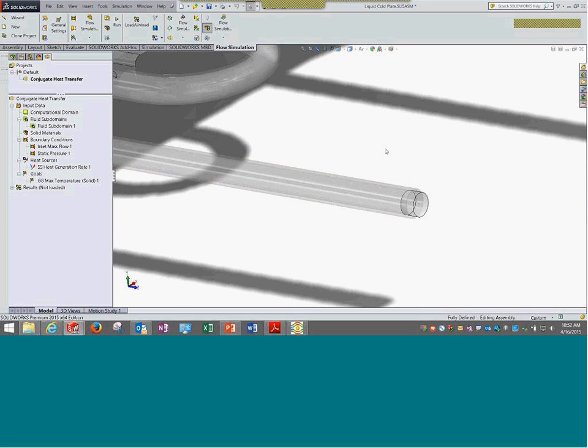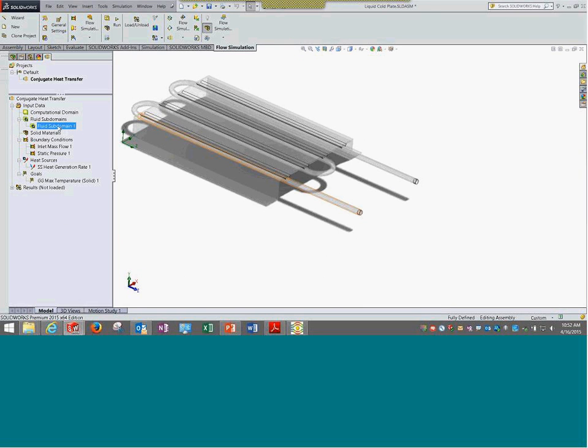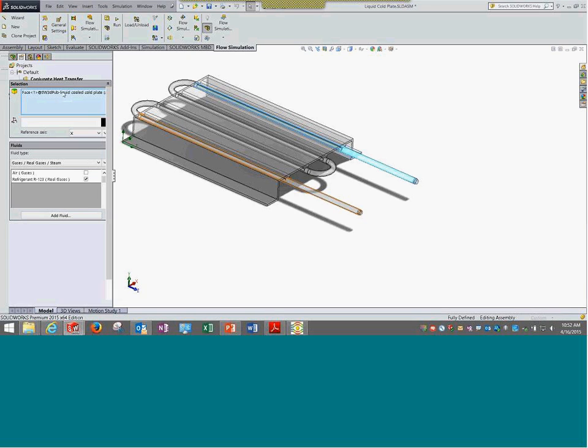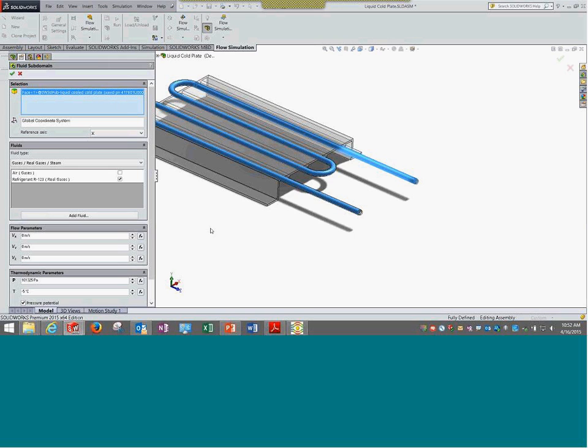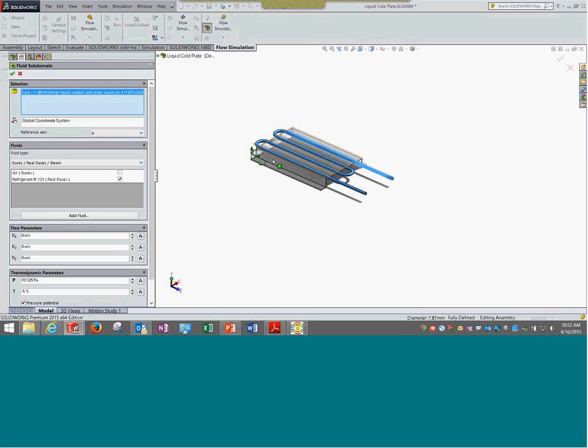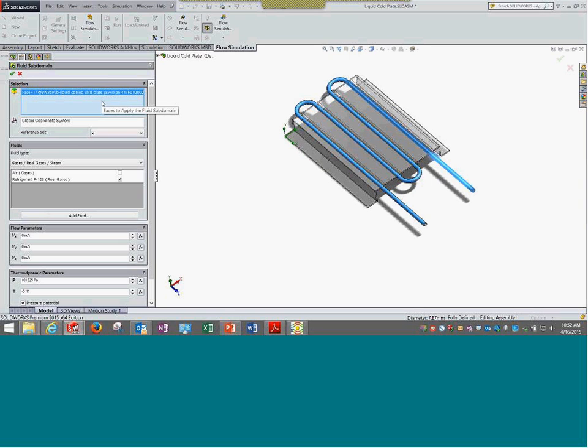It is something like this. Now I define the fluid subdomain. I select it. I take the pipe here. The way the software detects a fluid subdomain is, once it has an internal closed domain, something like this, we can select any surface in this particular closed domain.